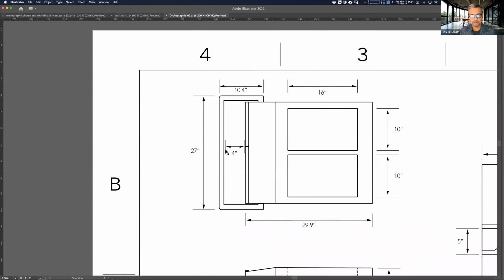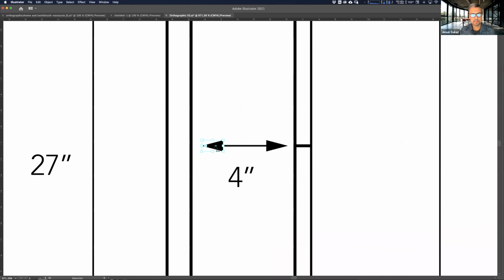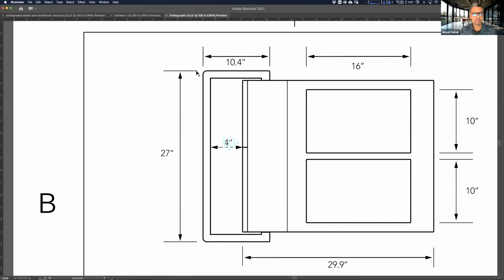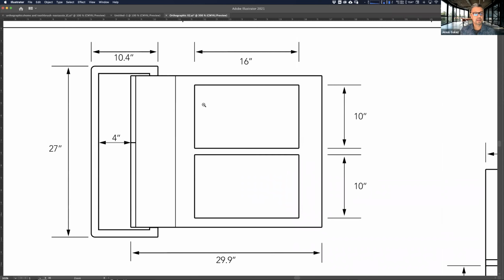It was good. Some of these things were maybe a little bit off in these lead lines here. I would probably extend this out, like this arrow. You can bring this out here and bring this out here. So something like that, and usually the number goes above it, so it's okay to do that. The lead lines in this case were pretty good, probably just a little bit closer, but pretty much in line here.